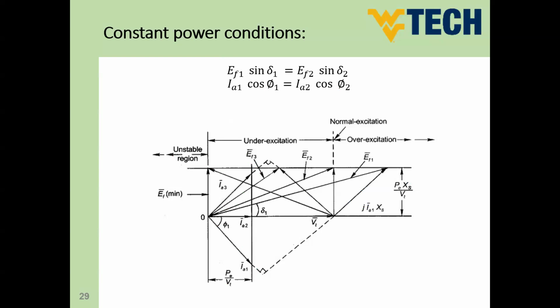So in order to keep the load working, you may have different requirements from the load. You may have different requirements from the reactive power. You may need to change the excitation, and excitation is not changeable automatically. You have to control that. Or if your load is increasing, you need to control the excitation in order to achieve a certain loading condition.